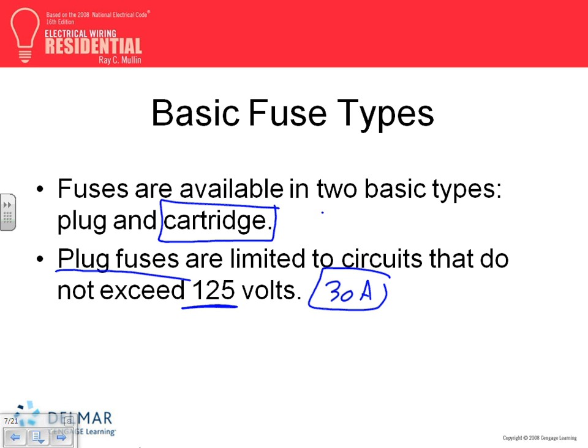These guys, you can get them from close to 300 volt or 600 volt, and you can go from, I don't know, 1 amp, but I'm going to say from 0 amp all the way to 6,000 amps. Now, Spencer, here's my 4,000 amp switch gear. When you size a 4,000 amp switch gear, they're going to ask you, okay, Spencer, what type of switch gear do you want? Do you want a fused switch, or do you want a circuit breaker? And the difference in price, guys, the circuit breakers are almost double at the higher level. So that's where they're going to ask you.